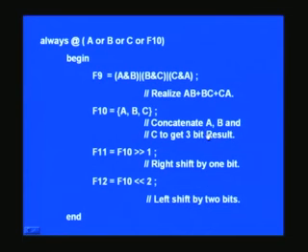Now, what we have seen over 2-3 pages, we have contained the entire thing in a single page here, the program as such. In fact, you recollect what we had done earlier is we have realized the majority logic, which is AB plus BC plus CA. So, note that ampersand stands for AND and vertical slash for OR, and that is how you get AB, BC plus CA.